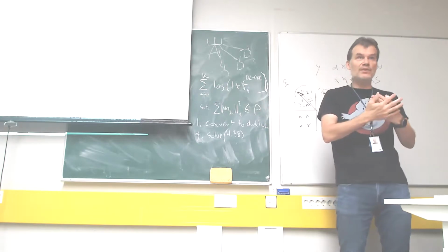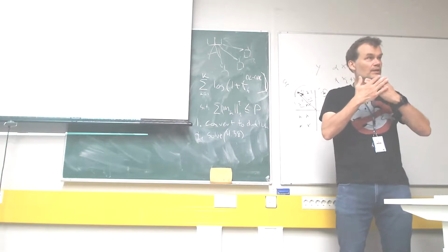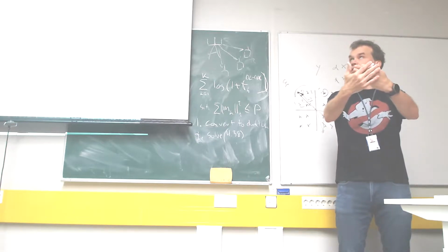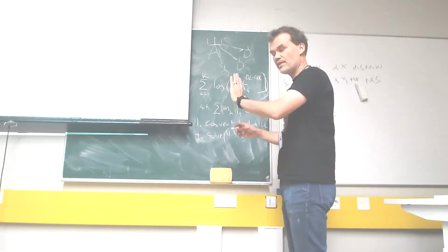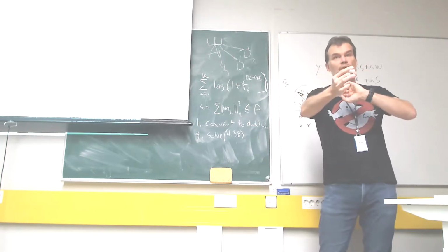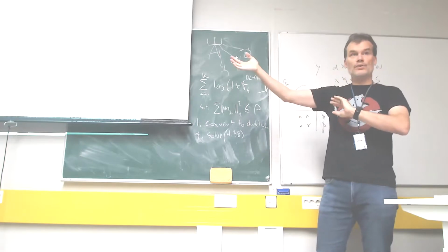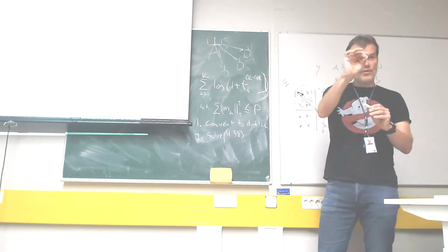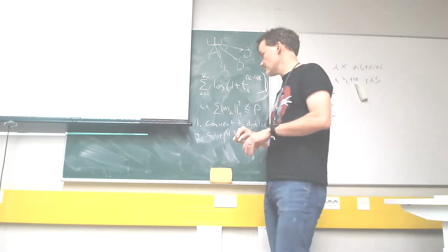The lowest priority user should be decoded first, meaning encoded last. So now you have decided a certain decoding and reverse encoding order. But this has to always be reversed for the duality to hold. That's a must. Encoding order is reverse decoding order, and vice versa.